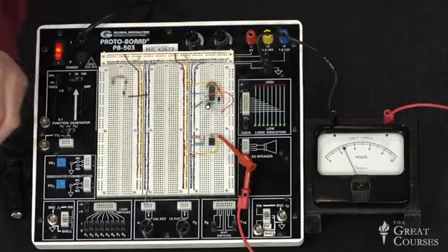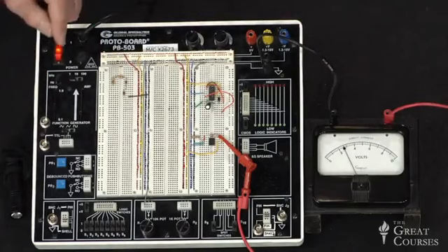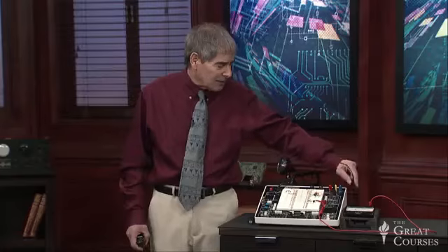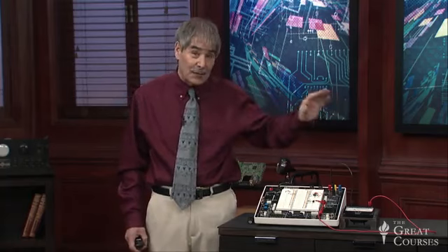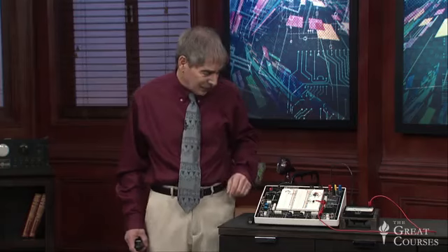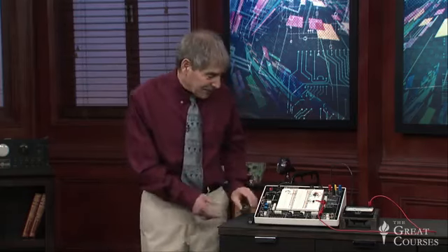The other difference is, because this voltmeter reads only positive, well, I could have switched the leads, but that would have looked confusing. So because it reads positive, I've actually turned the phototransistor around, so it's going the other way. I've connected the emitter at the top, and I've connected that to minus 15 volts, in fact, and I've connected a resistor to limit the current so the phototransistor doesn't get too much current through it. But it's basically the same circuit I've just shown you. And let's take a look.